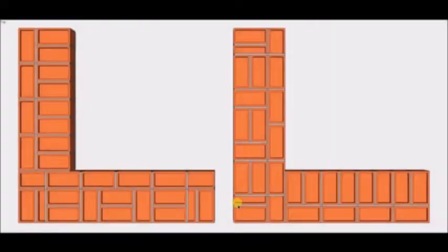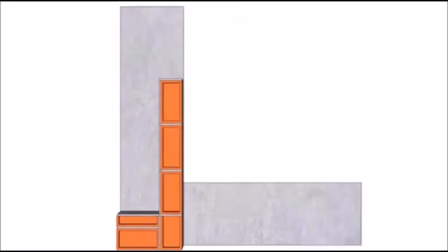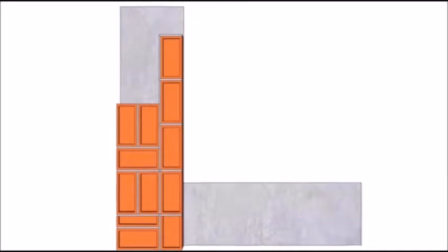Now, let's understand the arrangement in course 2 of 1.5 brick thick single Flemish bond. In course 2 we start from a stretcher instead of header, and then we place queen closer and a 3/4 bat after that. Now, opposite to course 1 in the same side of the wall, we place stretcher inside, and headers outside to break the vertical joints.